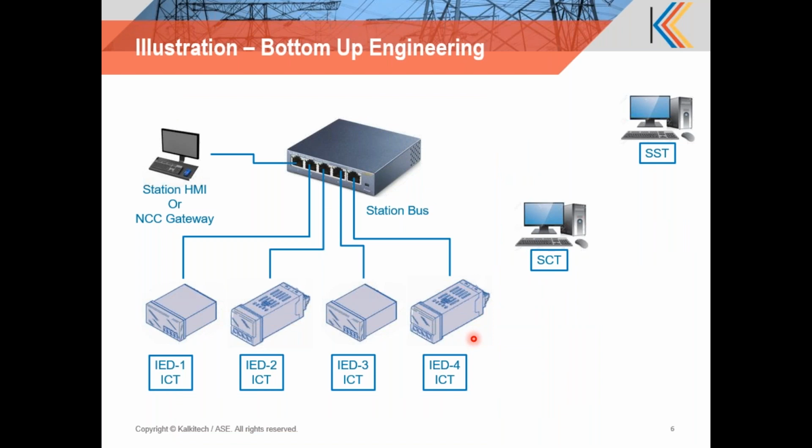So salient characteristics of top-down engineering are: 1, the usage of a standard specification; 2, ICDs being used as templates containing the IED capabilities and brought into the SCT, where all the engineering is actually performed; and 3, the output of the SCT is piped back to the ICTs, and that is what actually ends up configuring the IEDs. As you see here, all these points are contradicted in the bottom-up approach.